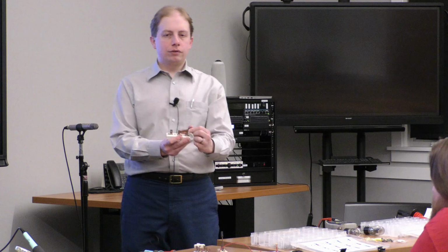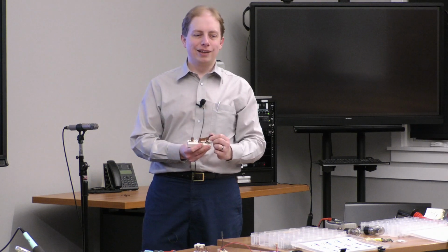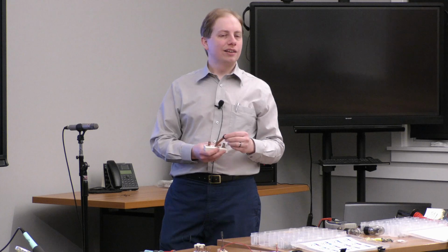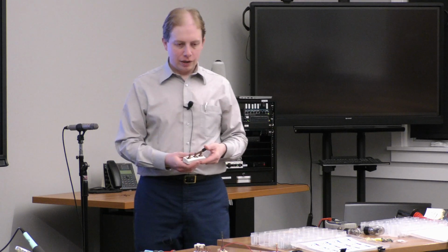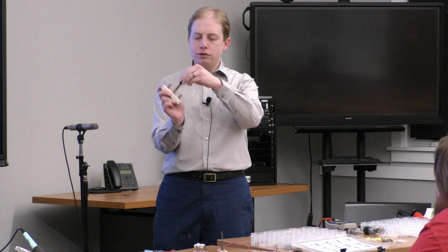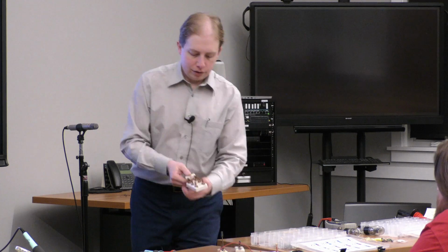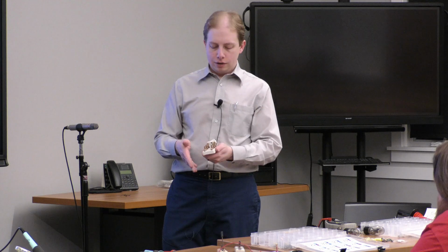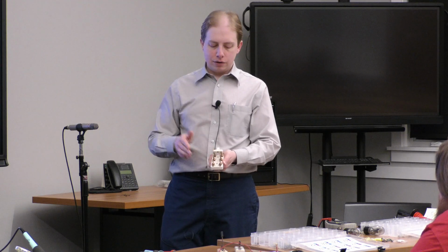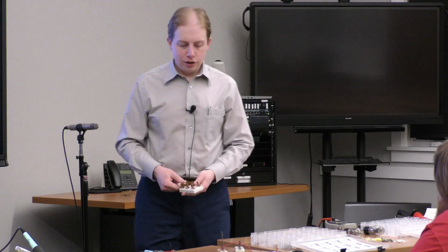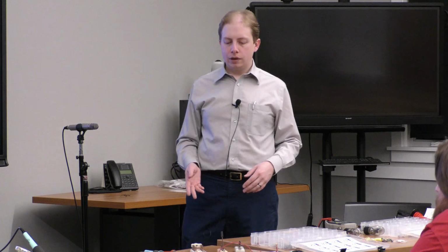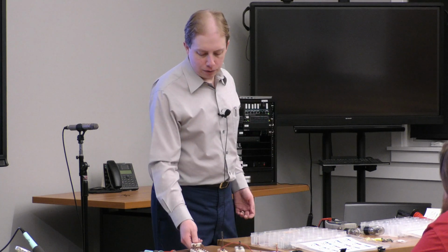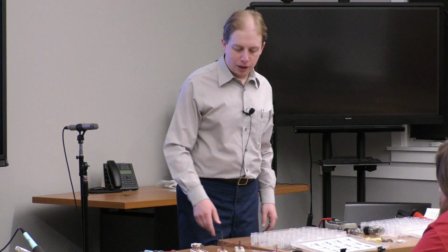This switch, you can move. This, you still only have one blade, but you can move it two different directions. So that's a single pole, double throw switch. Now this one has two different blades that are insulated from each other, so that's a double pole. This happens to be a double throw switch. You could also have a double pole, single throw switch. You can have as many poles as you need. You usually only have single throw and double throw. But it is important to understand that terminology for the test.